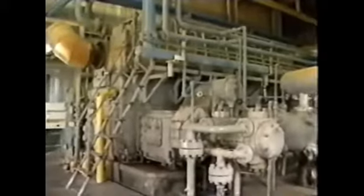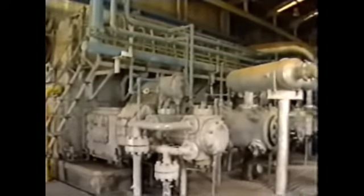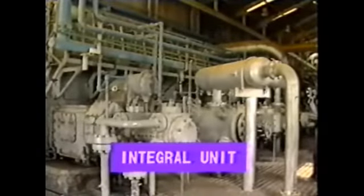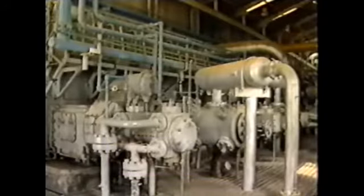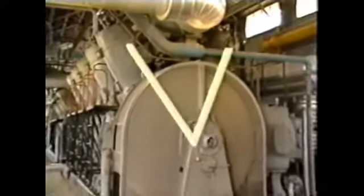When the compression unit and power source are on the same frame, the term applied is integral unit. In this arrangement, the compression unit and power source share the same crankshaft. The compressor cylinders are usually horizontal. The power cylinders, on the other hand, are either vertical or at a V angle to the horizontal.